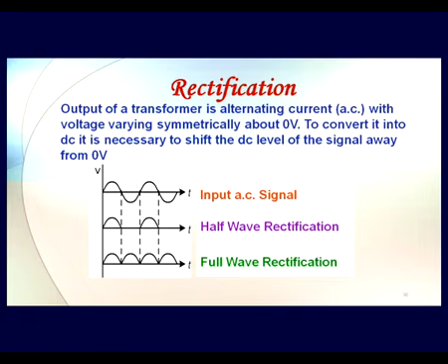This is done in case of half wave rectifier. There is another type of rectifier, and we will be describing it in quite some detail, the full wave rectifier, where we are making use of both the half cycles of this sine wave that we are given at the input. That is, the positive half cycle is passed just like that, but the negative half cycle here is inverted and passed through it.